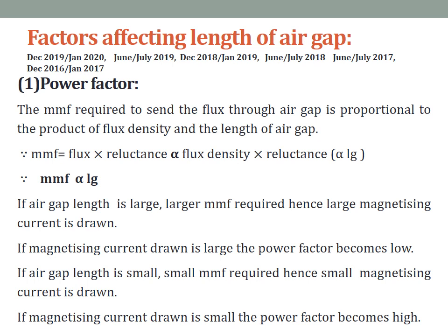It may also be possible to have a larger air gap length. If you have precise manufacturing technique, the air gap length can be minimized. If there is no facility, no precise manufacturing, no advanced techniques, the length of the air gap becomes large, because the rotor has to rotate in the air gap.